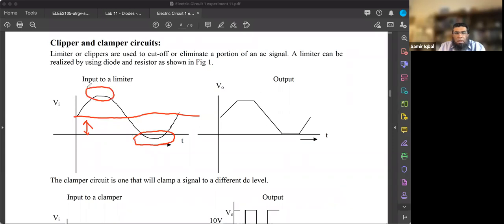So we can restrict how much voltage can go through this circuit. So a diode can itself become what we call a clipper circuit. It can limit and or cut off how much voltage can pass through, because it would be reverse biased on those locations.